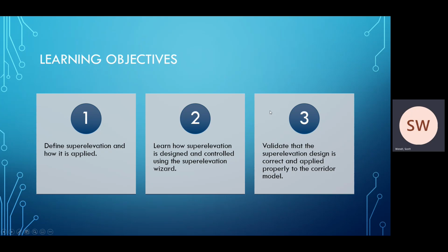So a couple things I hope you learn today. First, how to define superelevation and how it's applied. Second, how superelevation is designed and controlled using the Superelevation Wizard in Civil 3D. And third, how to validate that the design is correct and applied properly in our corridor model.